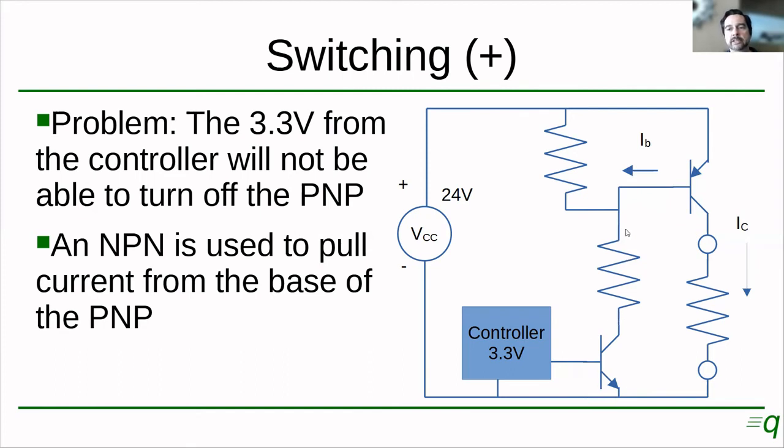It may have some microamps of leakage here, especially at high temperatures. So by providing another resistor here, we are providing a path for the leakage current of this transistor through this other resistor, and so it's not coming from the base. There's still going to be a little bit from the base, but it's going to be greatly reduced, because this resistor is going to be providing most of it.